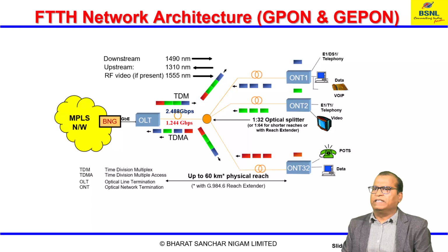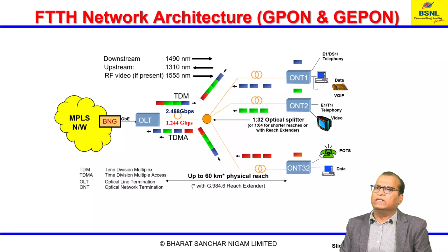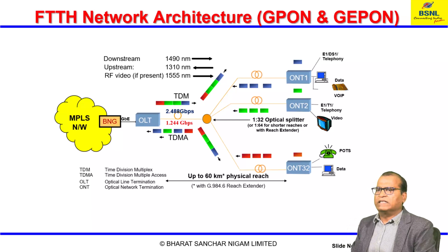So this is the FTTH network architecture using GPON. There you will find the OLT is deployed inside the exchange and the ONT is inside the house. The ONT has different user interfaces, where a user can connect their electronic devices. Between OLT and ONT, there are splitters, which split the light. It is using a single fiber.